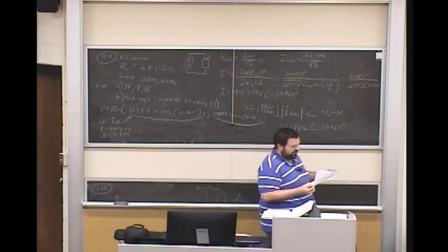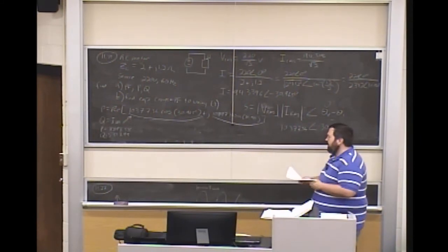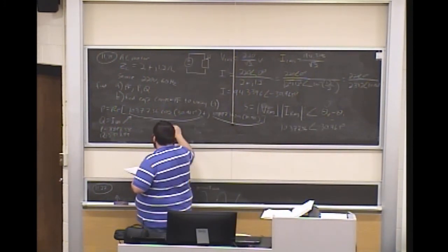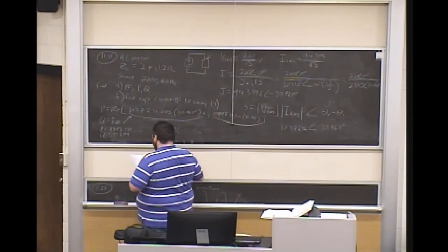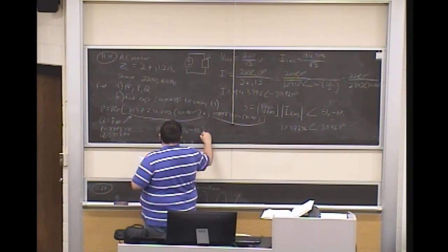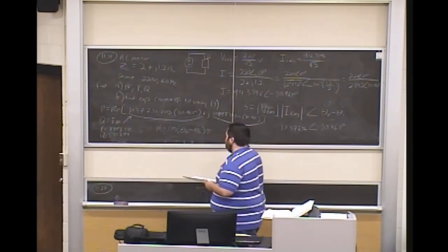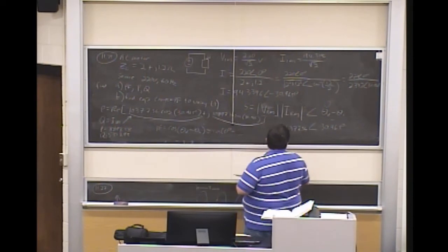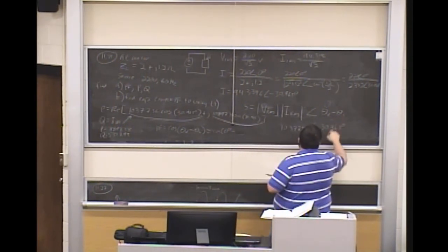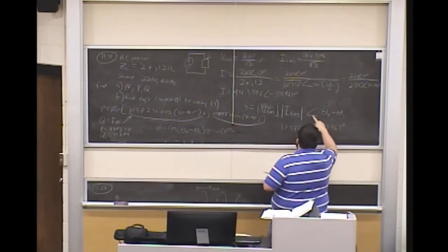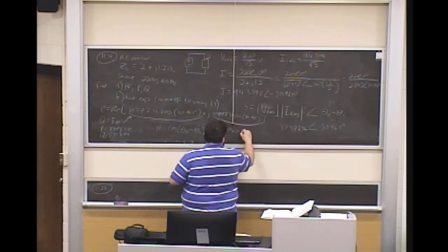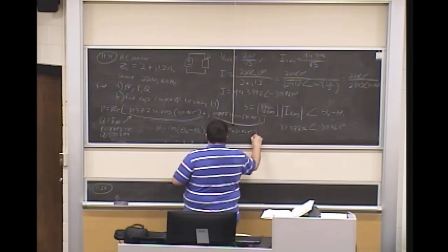And then the power factor, PF, is just equal to the cosine of the difference in angle between your voltage and your current. So that's just going to be cosine of 0 degrees minus a negative 30.963 degrees, so that's plus 30.963 degrees.